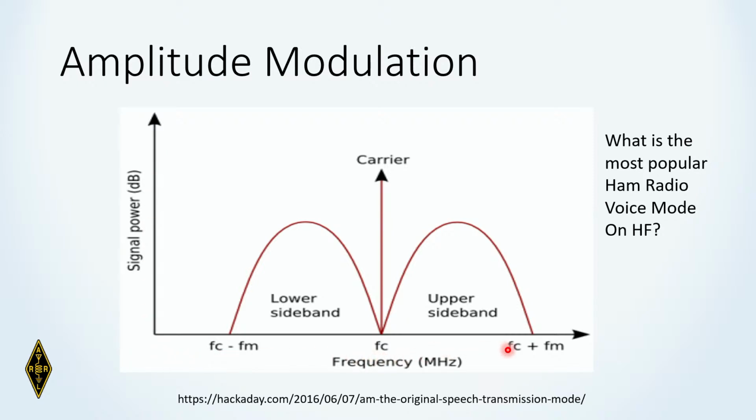And you might remember that an AM signal consists of 3 components: the radio frequency carrier, an upper sideband, which has the modulation information, and a lower sideband, which has the same modulation information, just reversed. Low frequencies are closest to the carrier. So low frequencies are here for the upper sideband, low frequencies are here for the lower sideband, lower modulation frequencies of the voice.